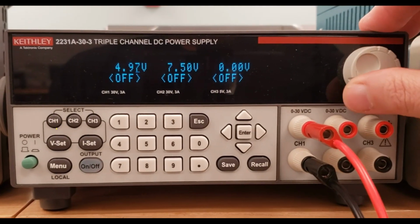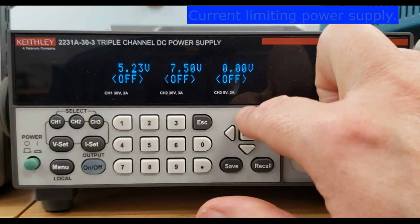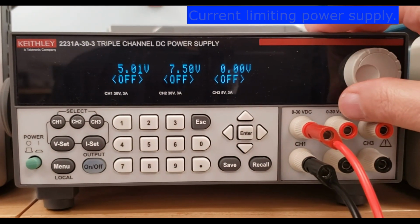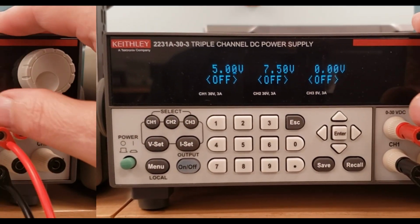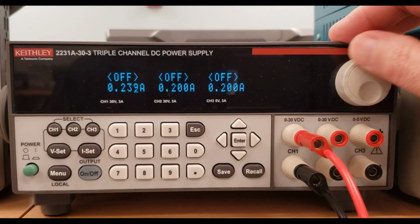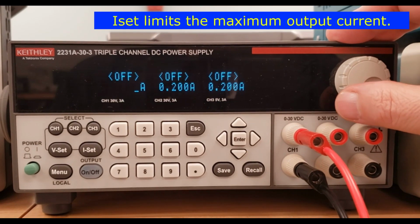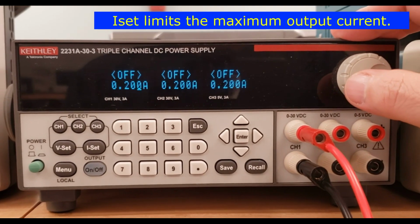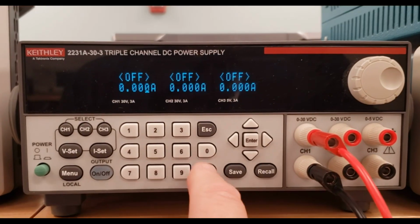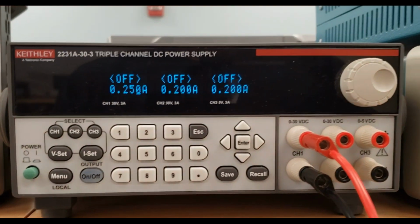We're going to start off by setting the supply voltage to 5 volts by pressing VSET, and then you can use cursors or the rotary dial to set it to exactly 5.0 volts. After setting the voltage, you want to set the current limiting by pressing I-set. And you can do that with the dial or with the keypad, so you can type in a value. And I believe in this example, I'm going to set it for 250 milliamps or 0.25 amps.